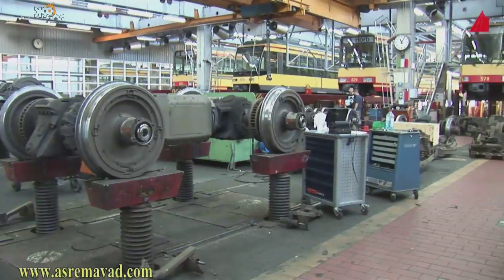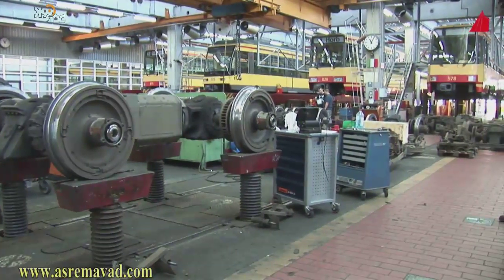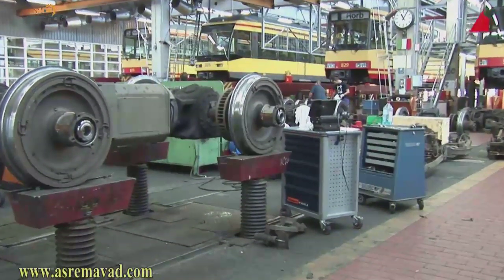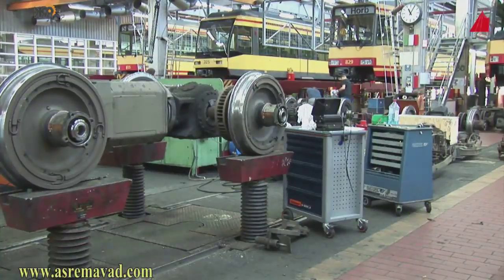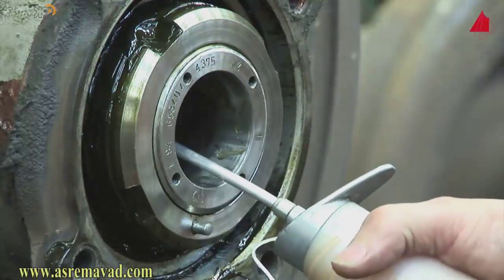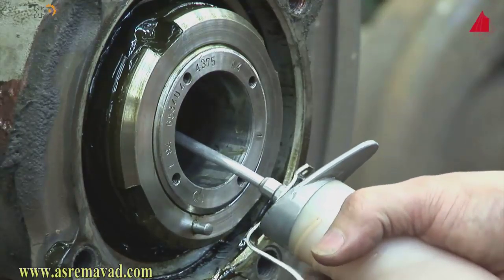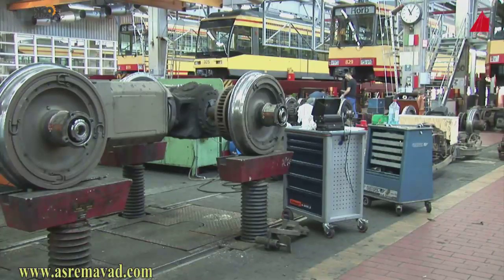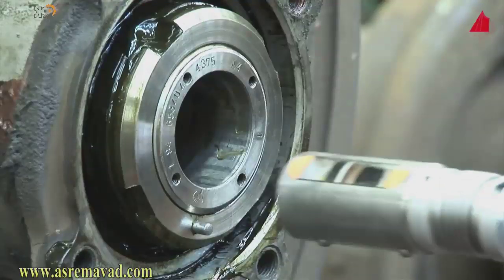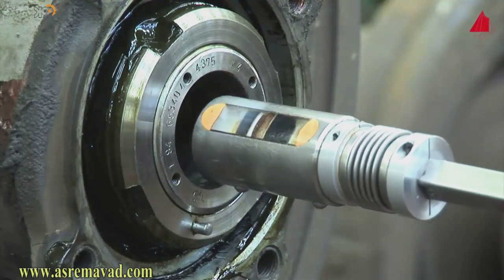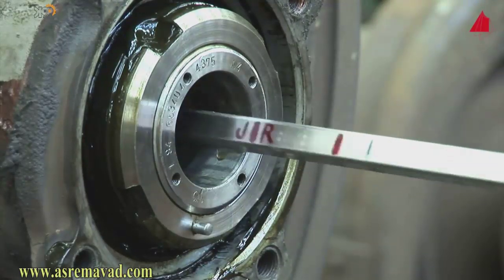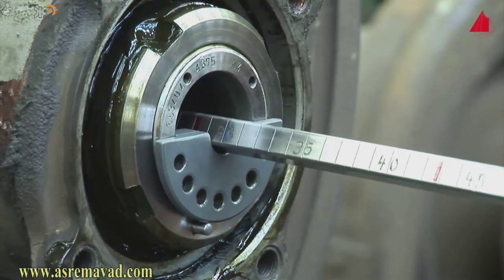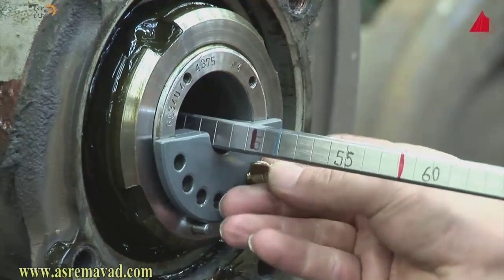Special attention is given to the wheel axle, among experts known as wheel set axle. It has been designed as a hollow axle. This saves weight and facilitates the ultrasonic examination. The material tester applies a suitable oil as a couplant into the bore of the axle. Now he takes a special probe designed exactly for this purpose, inserts it carefully into the bore with a mount, and evenly spreads out the couplant by turning and pushing. He has accurately marked the most important examination points at the mount.